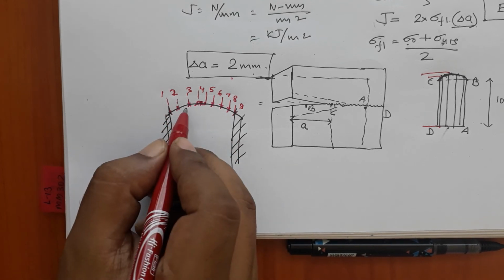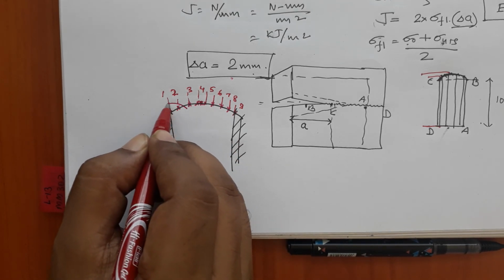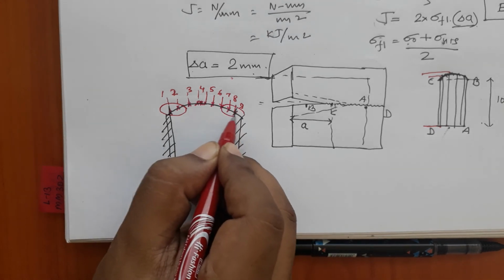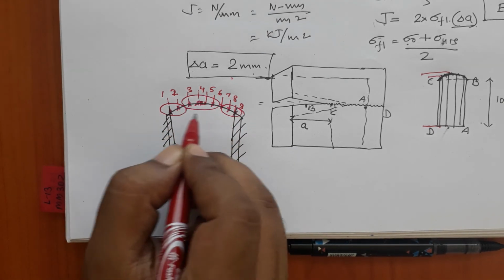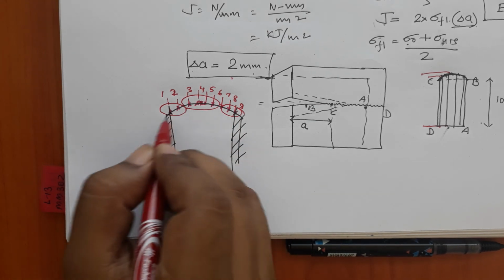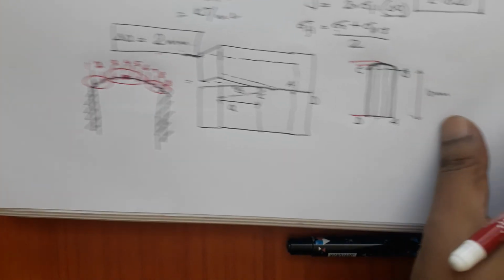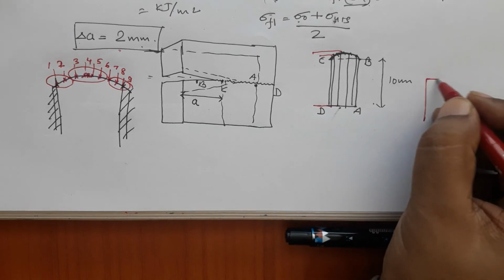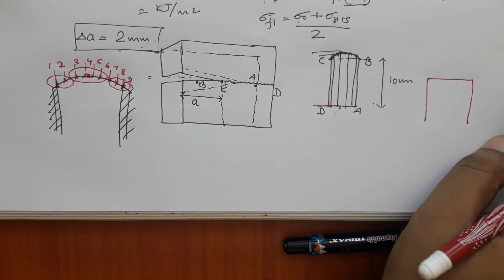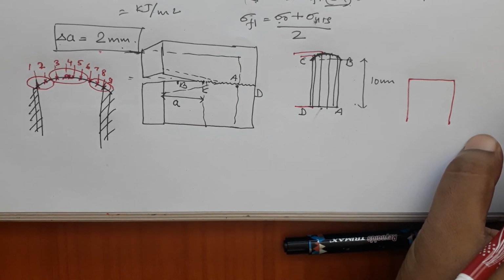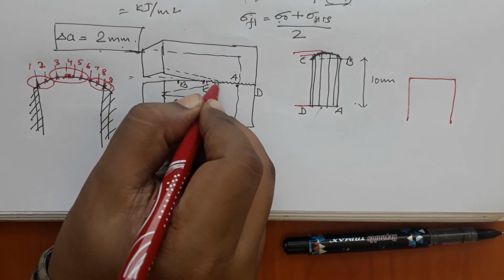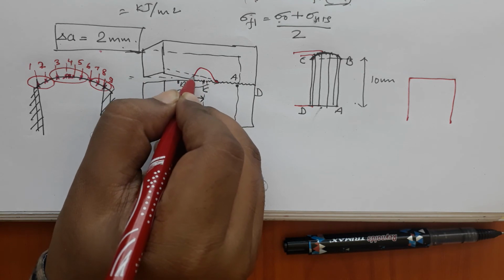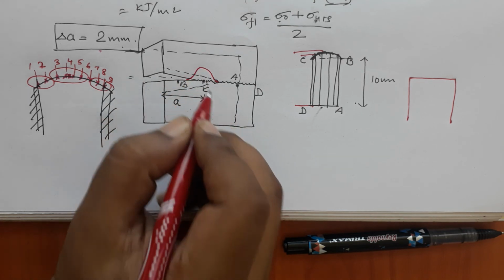We do not give equal importance to these points on the sides as we give the importance to the center point, because, and why are we getting this shape? Why the crack tip is not simply this inside the material? The reason is sigma ZZ, which has a distribution like this along the thickness, right.